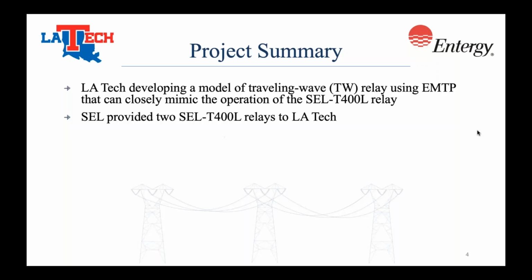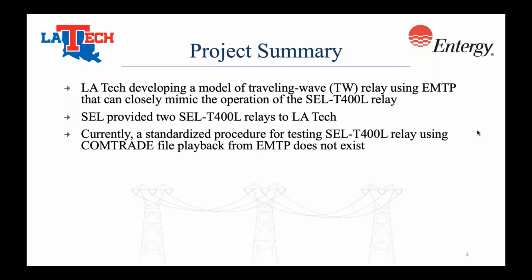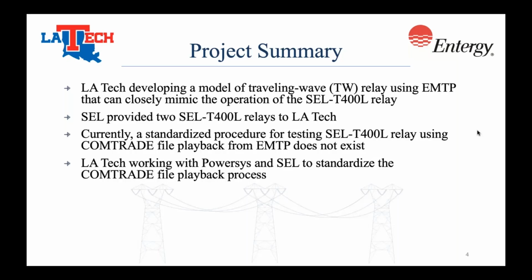As we started working on this in more detail, we encountered many unforeseen issues. The issues were arising due to things like, currently a standardized procedure for testing SEL-T400 relay using Comtrade file playback from EMTP does not exist. So LA Tech is working with PowerSys and SEL to standardize the Comtrade file playback process. Furthermore, we are also testing the beta version of a Comtrade file generator add-on to the EMTP library.